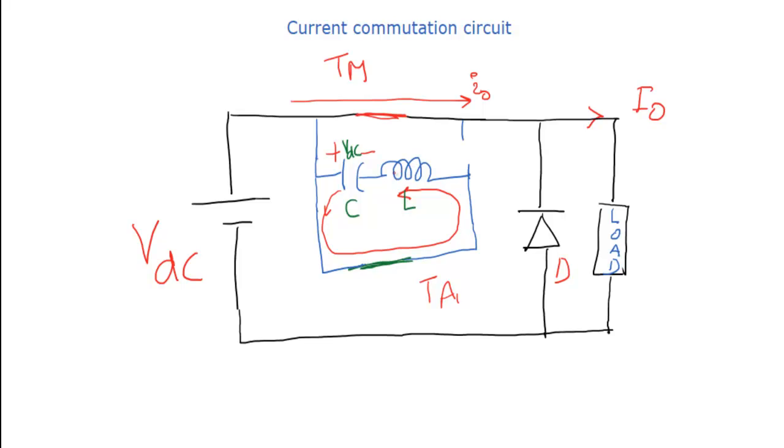During this process, all the energy will be transferred. That means the voltage across the capacitor will slowly reduce, and the current flowing through the capacitor and inductor, which are in series, will increase. As we already discussed, this is a tank circuit. In that case, the capacitor or inductor current will follow a sinusoidal waveform, but the voltage across the capacitor will follow a cosine waveform. After 90 degrees, or π/2 radians, the voltage across the capacitor will be 0.